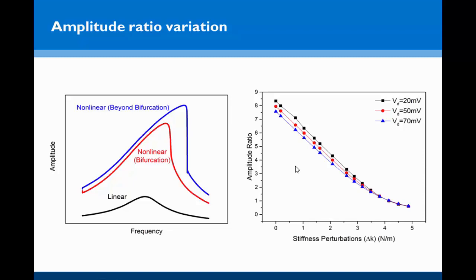And as prescribed by our simulations, we see that around veering, which is around here, which is the symmetric case, amplitude ratio 1, we see the best insensitivity to drive power variations, or it seems as if the amplitude ratio remains constant across different operating regimes, essentially.